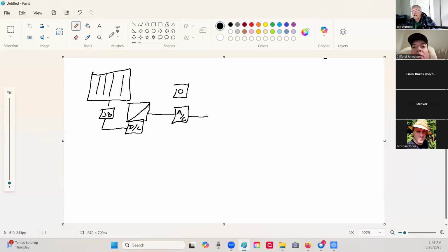From the AC disconnect, we're going to go into our service panel. That's your circuit breaker panel. We're going to connect into a double pole breaker. And then you've got the main, and the main goes out to the meter. And from the meter, you're going to go up to the telephone pole where there's a transformer. And that's your system. Okay.